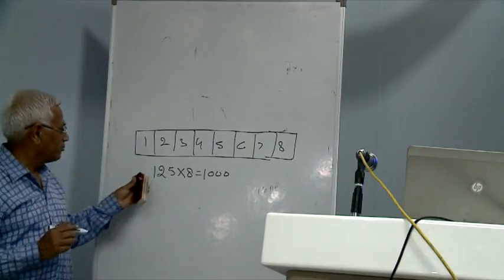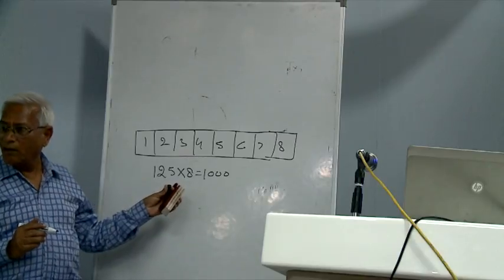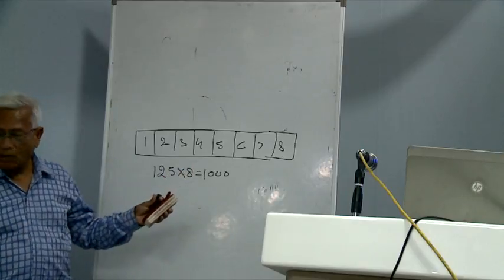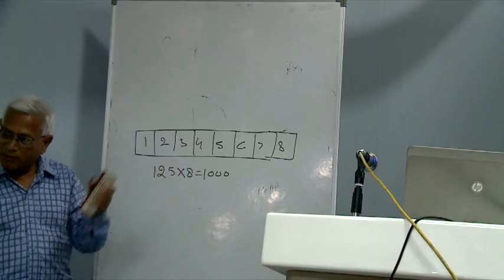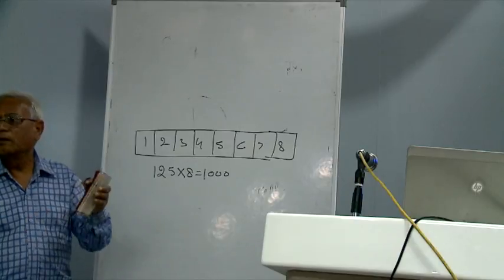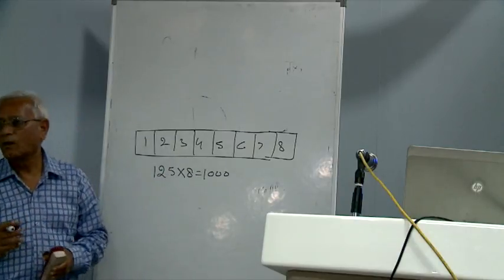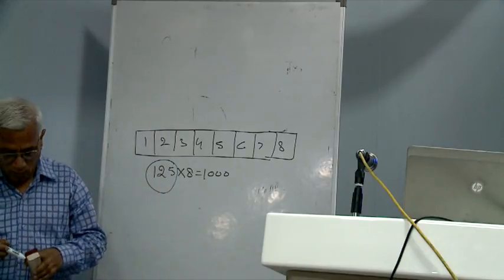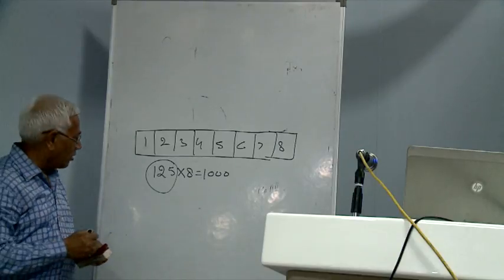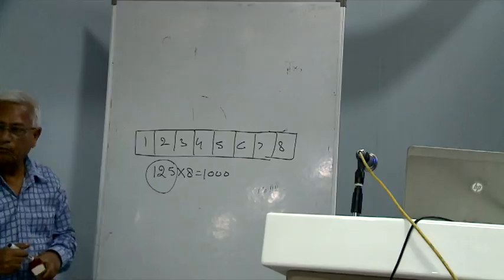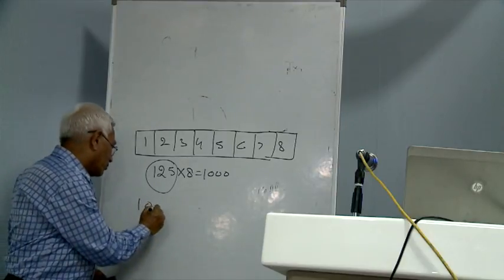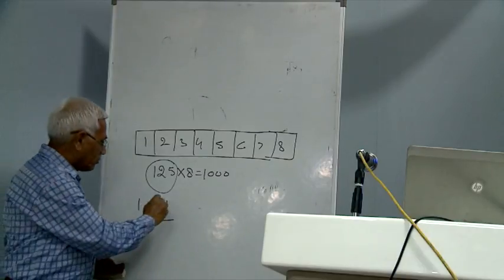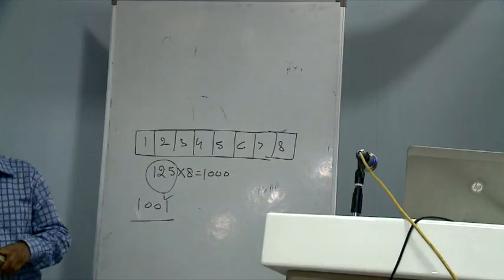That is the maximum. If the spectrum keeps decreasing, the number of users will also keep decreasing. This is based on 25 megahertz. Understand? For a 25 megahertz spectrum, the cluster size is bigger and 1000 people can talk. If the spectrum is low, this will also be less, because the channels will be fewer. So now the question comes: if it becomes 1001, we have taken the complete full spectrum. 1001 subscribers come in that cluster. What will happen to this subscriber? Will I be able to talk? I will not be able to talk.